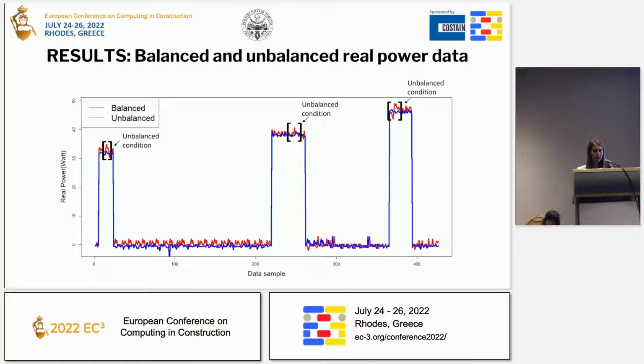With the red line, we can see the unbalanced condition. We can see 3 peaks that must arise from the unbalanced condition, as illustrated in this figure. When an unbalanced condition occurs, the motor consumes a large amount of power, which provides a threshold between balanced and unbalanced scenarios.